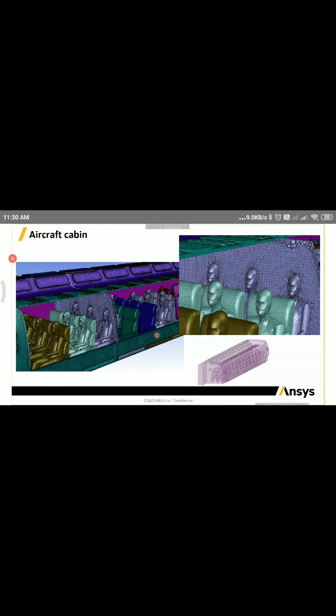By default you can use 4 cores, but if you have many cores, you can utilize them for the meshing. It requires physical cores, and that's separate from your HPC pack. So for the solver, you might be using the HPC, but for meshing or other requirements, you have to use the local physical processors available on your system. This is a Formula Student task, which generated around 70 million mesh count within 1 hour.